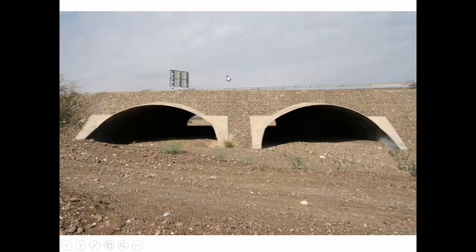And the reason why is they know that sometimes the water is going to be going through the culvert and it's going to be totally full, and then there's going to be even more water. So the water can either go through the culvert, or if it keeps getting higher and higher, it can go over top of the road. And so that's a condition that we're going to look at with the program as well, is how much of the flow goes through the barrels versus how much is going over the roadway.